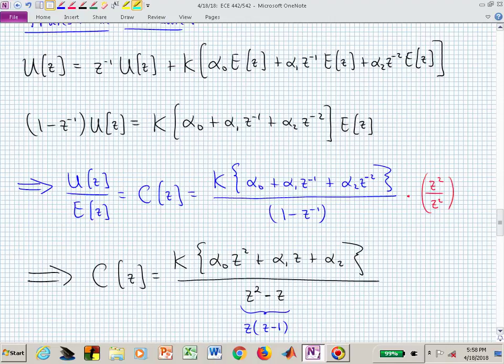If I say PID controller for a discrete time system, you immediately can put a pole where? At the origin, and another pole at 1. What's the pole at 1 do for you? Do you remember? So I've heard stabilize and I've heard zero error.